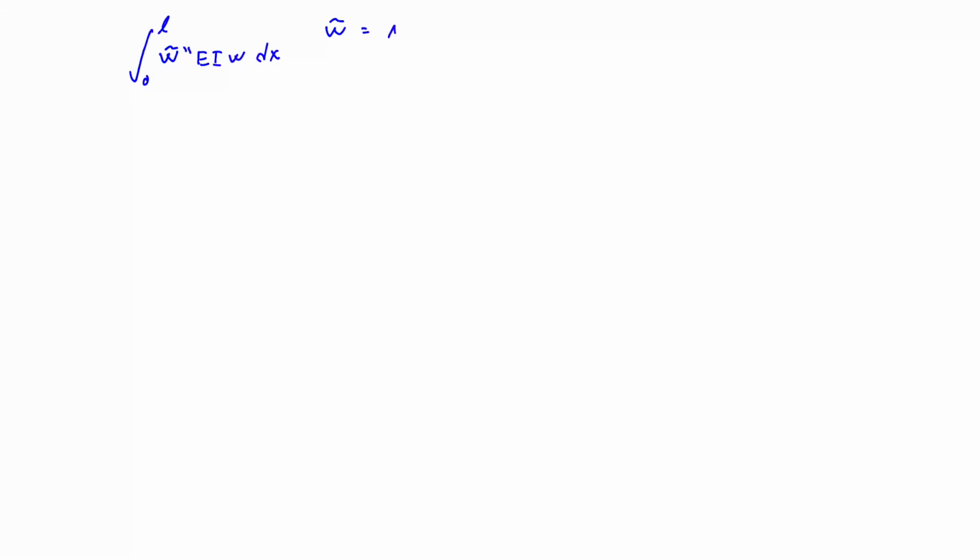That will be the shape function vector multiplied by the vector containing all nodal displacements, with a tilde. Because w tilde is a scalar function, we can, like for the cable, transpose these and still get the correct expression for w tilde. Then we also interpolate w, and this we do by the same shape function, but the nodal values are now without the tilde.